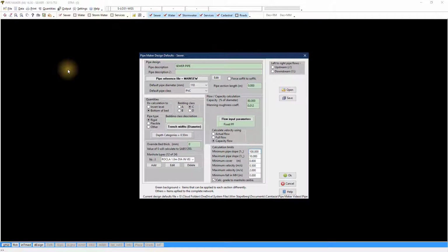modelmakerstrings.kcs. The first pop-up will be the design defaults. Change your settings according to the design. Make sure to select upstream or downstream. We did our design strings in ModelMaker going upstream. Select your pipe diameter and class or change to a different reference file. Choose the existing or add a manual definition.